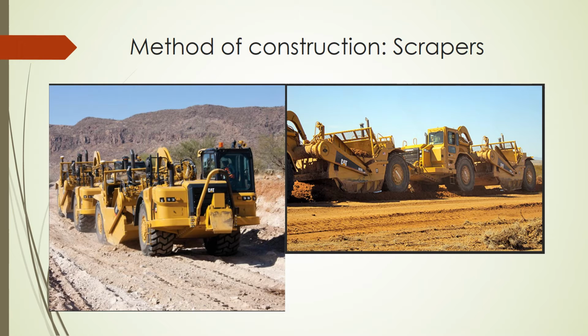operator levels. And you can see here a couple of scrapers doing push-pulling, which improves productivity by scraper 1 loading its hopper or bin, and scraper 2 pushing it, and then scraper 1 will pull scraper 2 whilst it loads its bin, and they can disgorge at the same sort of rates. It's a very effective way of excavating and constructing embankments.